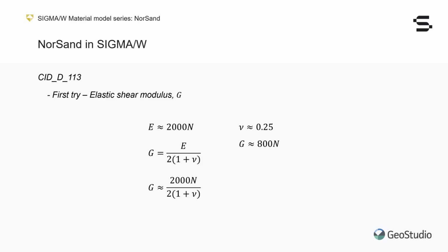Let us estimate that our somewhat dense sand could have an SPT blow count of 25, which would yield an estimated shear modulus of 20,000 kPa. While an N value of 25 would technically not be considered dense in the field, it would probably correspond to a dense sample built in the laboratory for a triaxial test. This is of course just a rough estimate to get us going. I like this method because I can genuinely get this estimate in my head just by remembering this simple relationship.